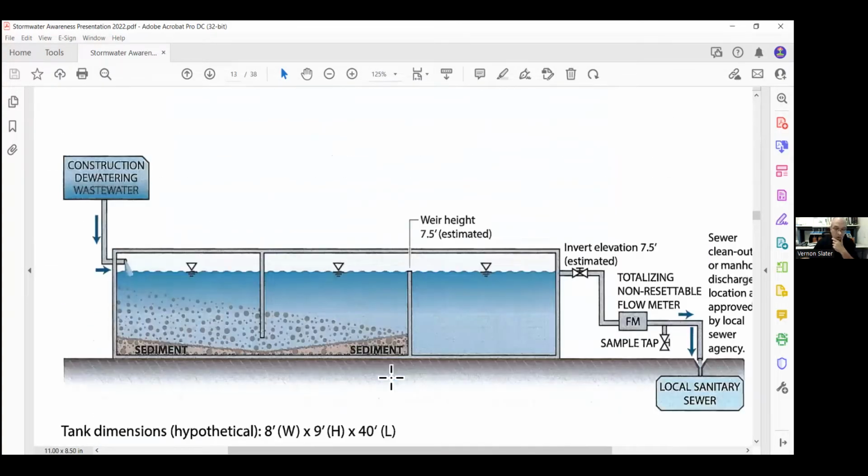Now the pre-treated water flows through a tank or basin for about 90 minutes of contact time. You'll see that we have an underweir here that forces particulate down to the bottom and allows the clean water to rise to the top to come over the overweir onto the other side and then off to filtration. In a typical one season small system site, 200 to 800 gallons per minute or less, treatment will usually be done in tanks. As water flows through the tank, it will pass by underweirs and then into an overweir. In basins, basin design is the most important.